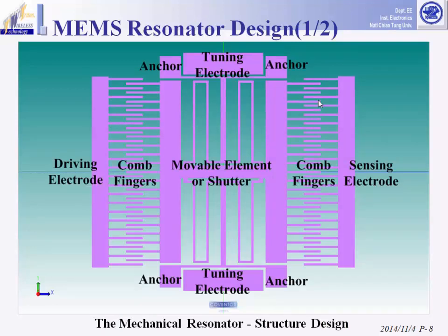For monolithic integration, the 4 anchors were placed at corners to avoid wire bonding. And the 4 symmetrical springs were connected to anchors through 2 clamp beams. Such architecture could provide another degree of freedom to release the residual stress. And the white light interferometer had shown smaller curvature as expected.